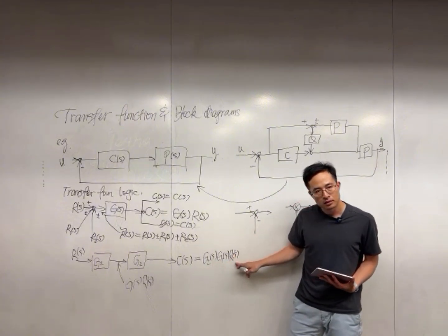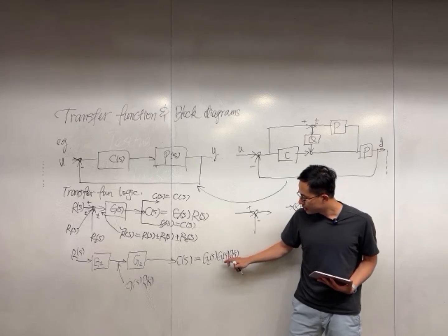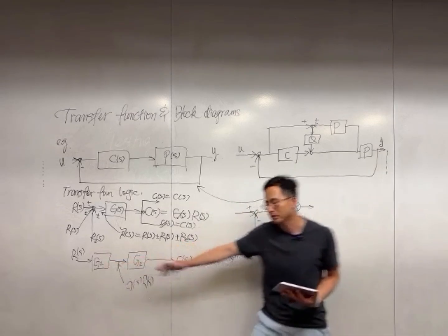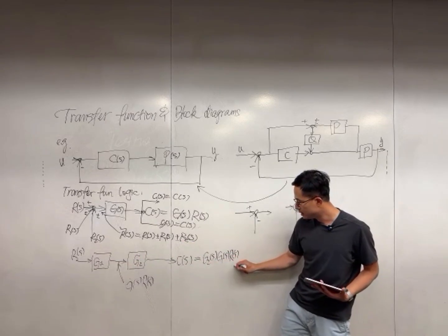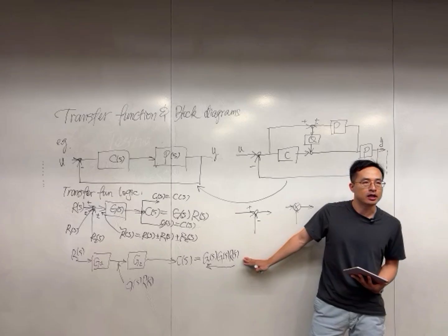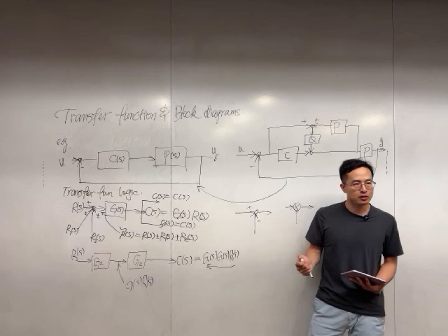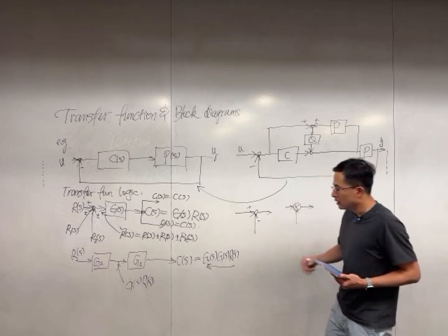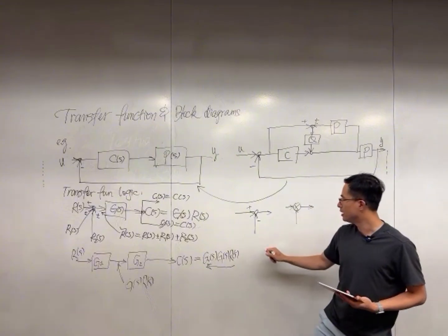So input on the right-hand side, put it at the end, and then the second to the last item is the transfer function. So think of it this way: this signal hits G1 and then hits G2. So in this series, write it this way, okay? This matters not much in linear systems with single input, single output. But if you step into multi-variable systems, this is extremely important. You follow this convention. So that is in series connection. You can also do in parallel connection.